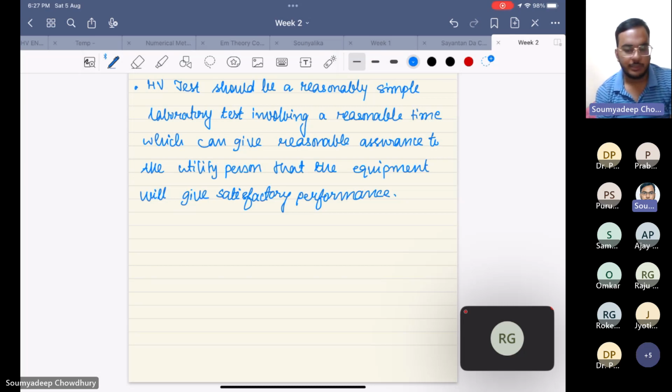And as you all know, these birds will not get shocked because both their legs are at the same potential, so no current will flow. Hence they can easily sit on these transmission lines. So these bird droppings will also deposit on the surface of the insulator. If you analyze the excreta of the birds chemically, it has been found that some conducting materials are there because ammonia is present. So this will obviously alter the conductivity and the performance of that insulation.